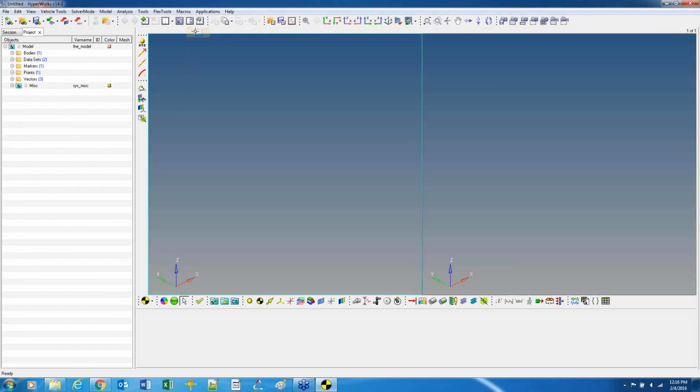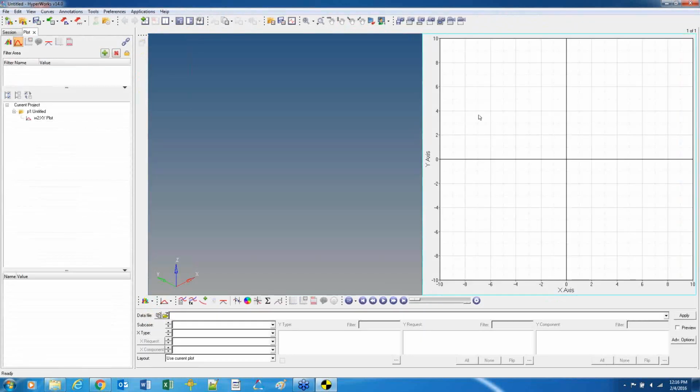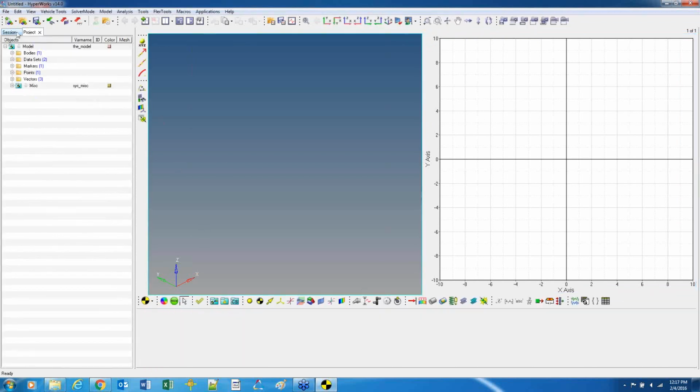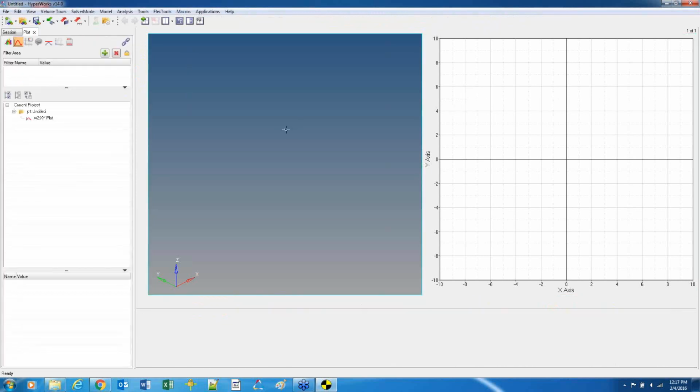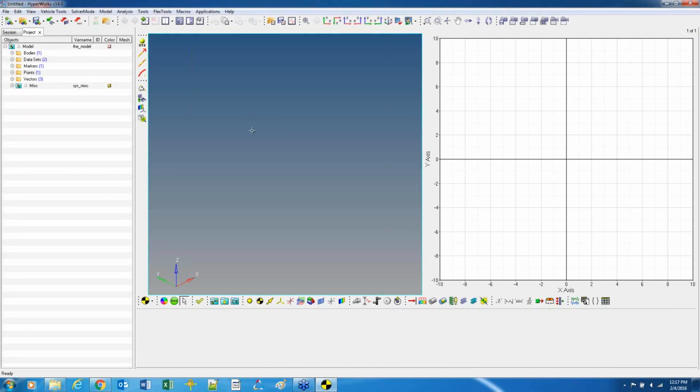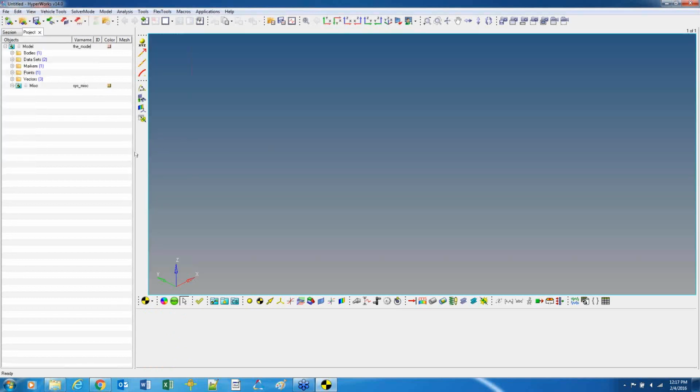So again, if I go here to switch over and I make my second window a HyperGraph window, then you'll see that this is now called the plot tab, and that's the browser for controlling the plot. But if I go back over to a window for MotionView, then you see that you have the tab that's a function of that. So this toolbar down towards the bottom, as well as the browser, tends to update based on which window you have active and that you're working in. And so that's really the big picture of this overall framework, that the MotionView window, as well as HyperView, 2D and 3D plotting, HyperMesh as well, and even some additional capabilities like table views and text views are all optional window types in there. So let me do, again, a clean refresh.